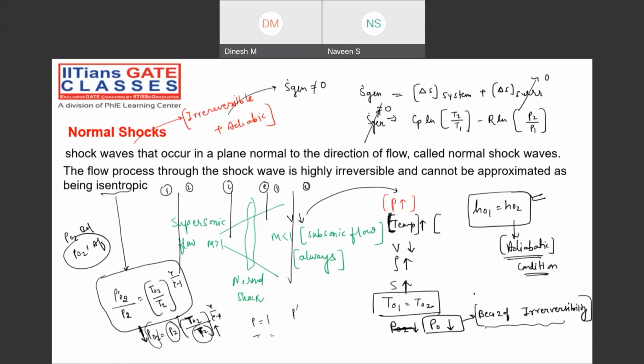If you are not able to understand by this particular meaning, that is why I'm explaining in that way, right? Because everybody can understand why the temperature will increase, because h plus u square by 2 is constant. So whatever the decrement in the velocity, that will be the increment in the what? Enthalpy. And enthalpy is a function of what? Temperature for the ideal gas. As far as the ideal gas is concerned, enthalpy is a function of temperature.